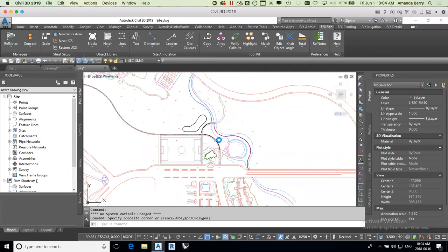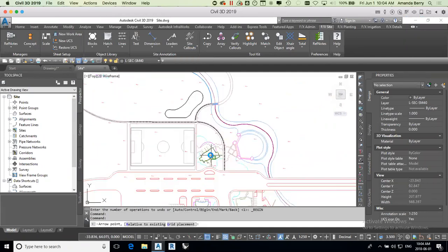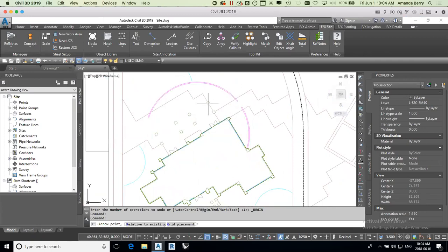So I'm going to go in, I click that point, and let's go into this plaza area. Plazas like this are probably going to be fairly flat. So this design probably won't need a lot of cut and fill analysis and heavy grading analysis. So usually when I was doing it, I would just end up using the spot elevation and slope callout tools to basically help me out with my regular hand drafting. I start out every grading plan with hand drafting.